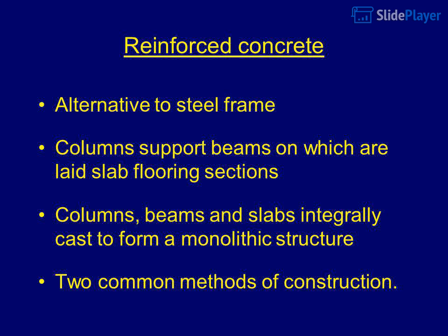Stanchions: reinforced concrete alternative to steel frame. Columns support beams on which are laid slab flooring sections. Columns, beams and slabs are integrally cast to form a monolithic structure. Two common methods of construction.